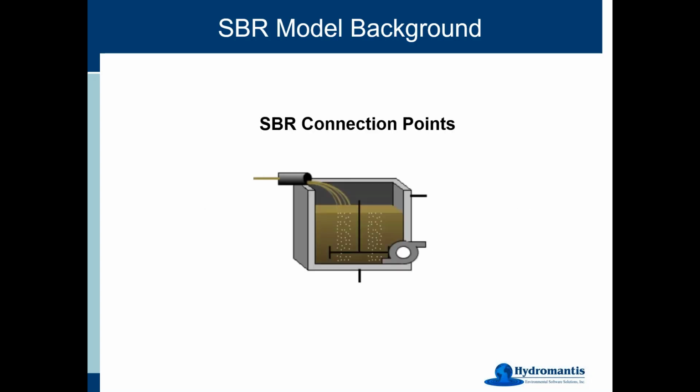So if you drop one of the SBR units on your drawing board, it has an influent, just like any one of our tanks. Although it's important to remember in this particular unit, unlike our regular completely mixed tank, the influent isn't always on all the time. In fact, you only want to fill for a portion of your cycle. So the control of the upstream flow coming into the SBR object is important, and we'll talk about how to control that properly. The bottom connection point is typically where people would be doing their wasting from. The decant pump on the side is where you get your treated effluent from.